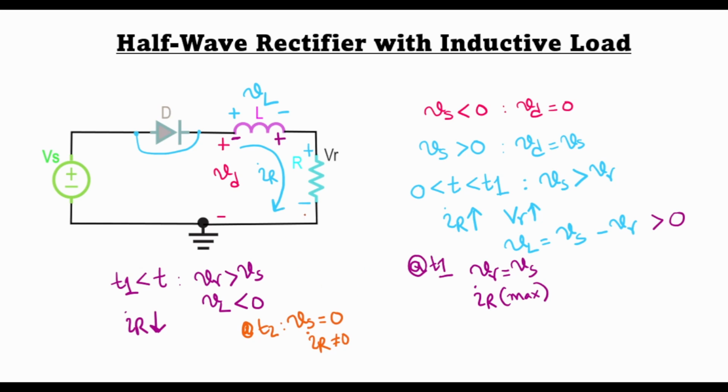And how do we know when the inductor has released its energy back to the system? This we will see from the plots that I will show, that in essence the volt second area during the charging phase should be equal to the volt second area during discharging.